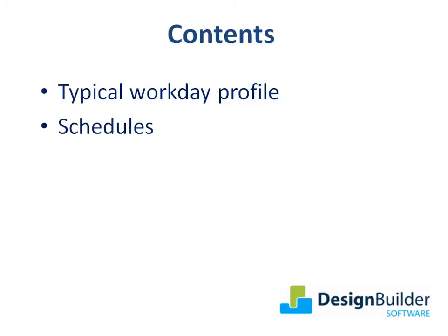and schedules, which are the default timing option. These can take longer to set up but enable more flexible modelling of occupancy and operation to better reflect variable occupancy patterns, internal gains and HVAC system operation. And finally I'll look at holiday settings.